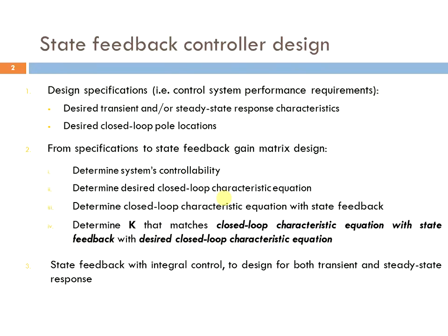We saw that if we just focus on the transient response characteristics, we might end up with a system that does not perform so well in terms of the steady state accuracy. One way of dealing with that is to combine state feedback and output feedback control. Specifically, we looked at incorporating integral control into our state feedback controller, so that we eliminate the steady state error for a step input to a type 0 system.